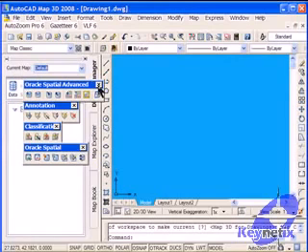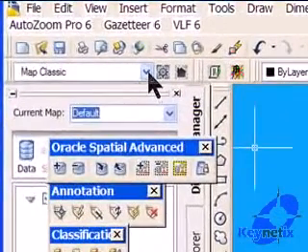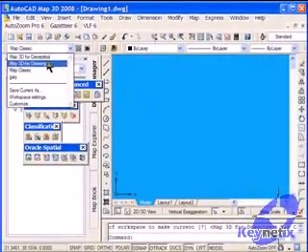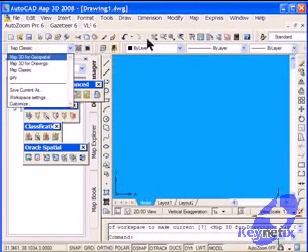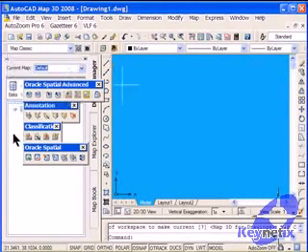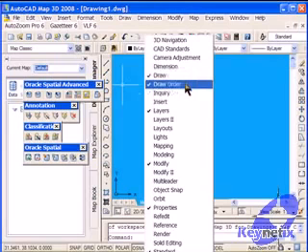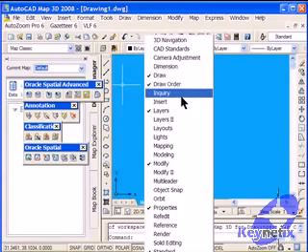Actually, what I'll do is a quick tip here. I'm not sure if you're familiar with this, but we now have workspaces. In fact, these came in AutoCAD 2007, and a workspace is really to save the look and feel of how you want to work, where you want your toolbars, etc. to be. If you haven't got this toolbar in, right-click on the toolbar menu somewhere. Unfortunately this is off screen now, but you should have a toolbar called Workspaces. If it's not on, toggle it on.